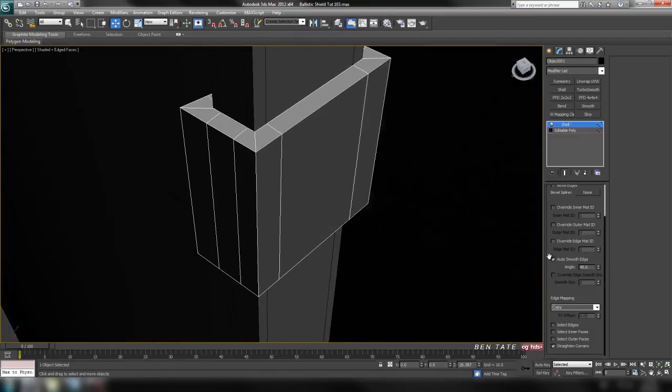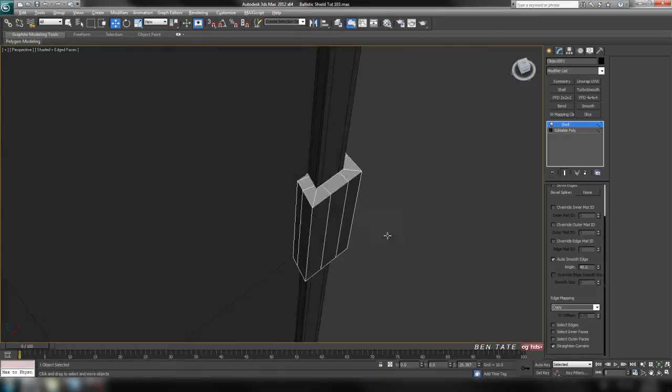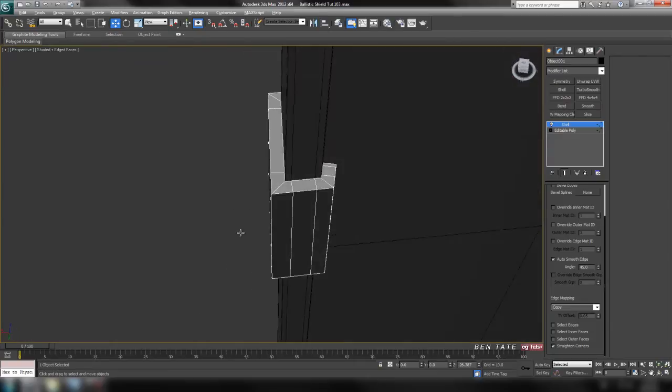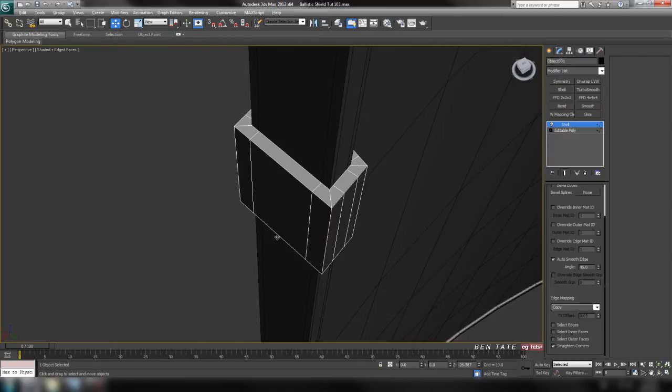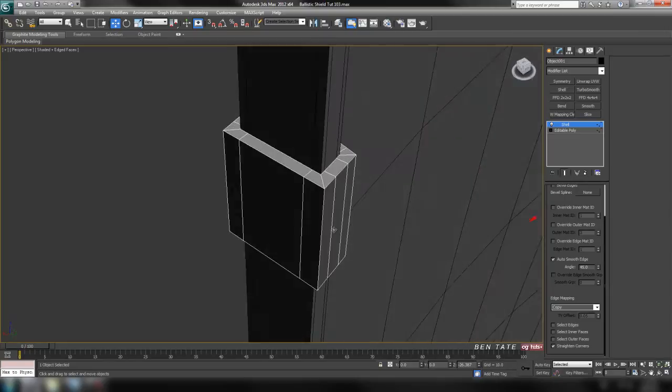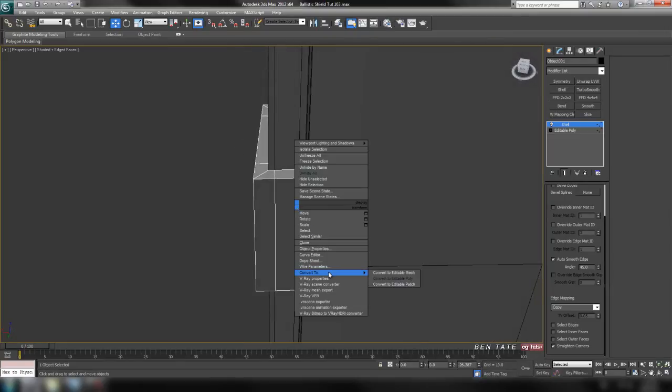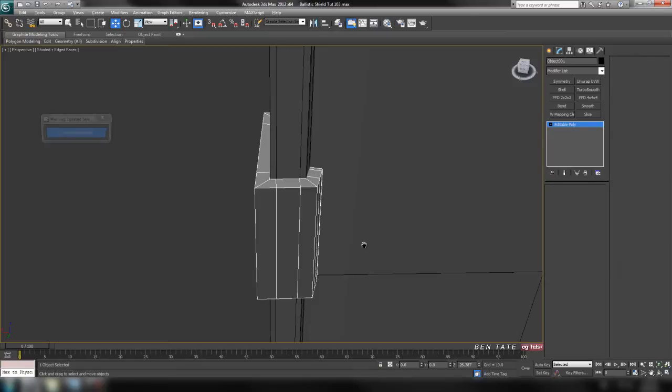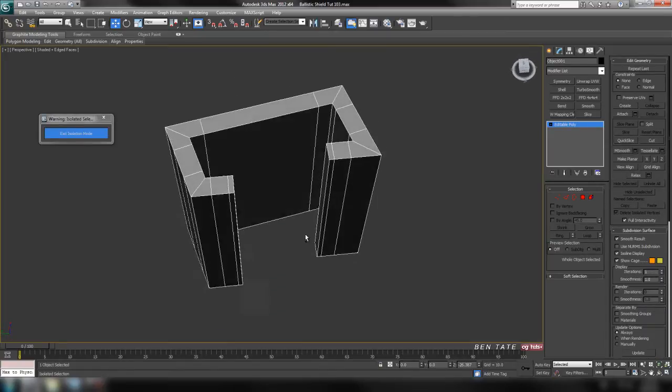Alright, let's also go down here and make sure we have straighten corners on, which we do. So that should work for our clip. We're going to need to make some adjustments to it here. We also need to extrude out some tabs. Alright, so let's collapse the shell down now. And we'll hit Alt Q, and we'll just have to clean this up a little bit here.